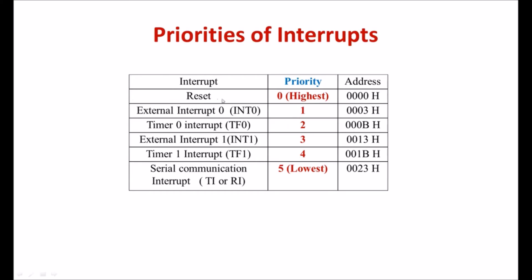The microcontroller will always execute the interrupt service routine written for the higher priority interrupt. So reset has the highest priority. Whatever the microcontroller is doing, if there is a signal at the reset pin, it has to provide service. It has to execute the program written at the address location of this interrupt, that is 000H.